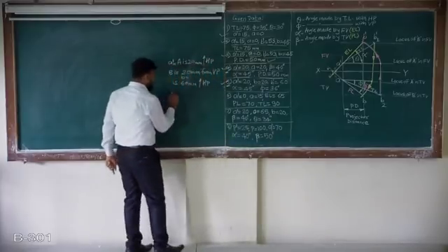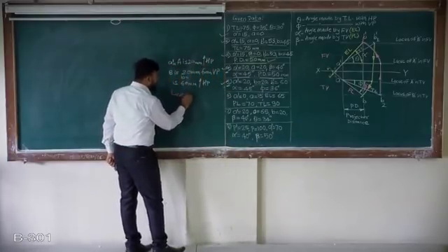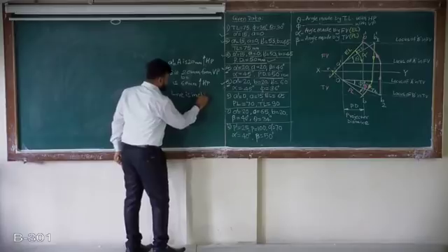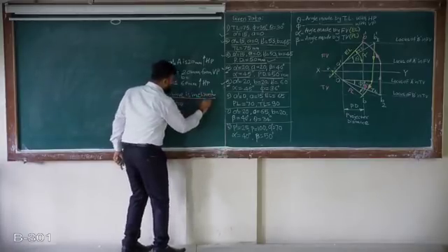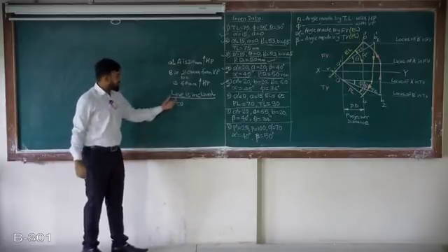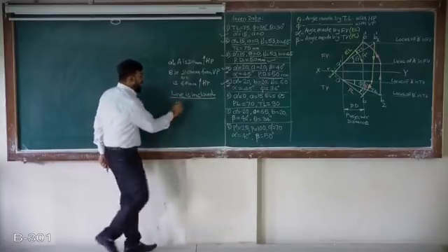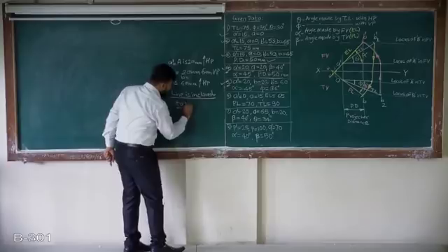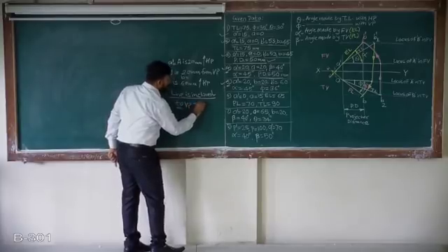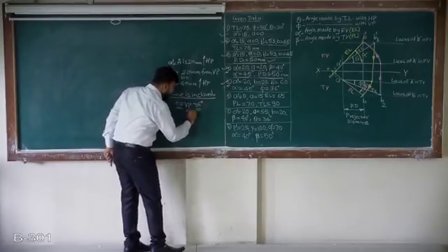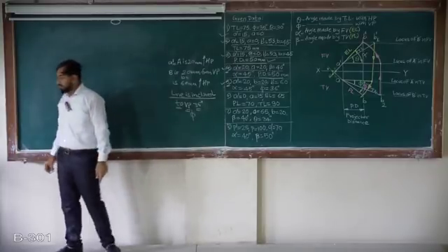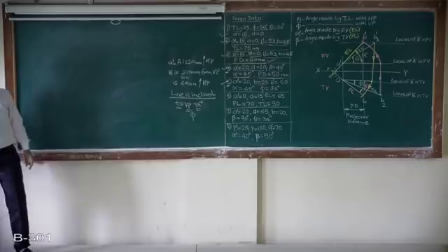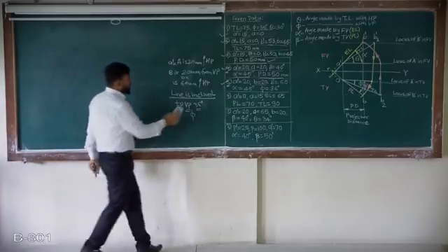So whenever the sentence says the line is inclined to, that simply means it is a true angle because it indicates the true length. So the line is inclined to, here it is VP, at 36 degree. So the corresponding VP angle is phi. So phi is a given parameter. I need to find out from this. You should identify these 5 parameters.